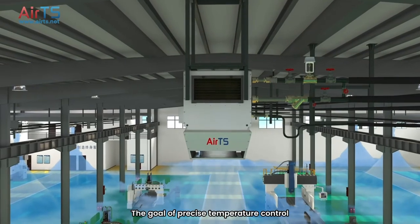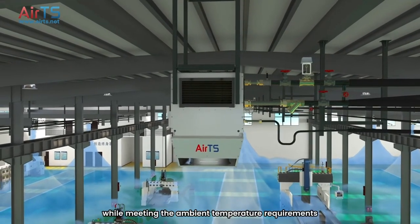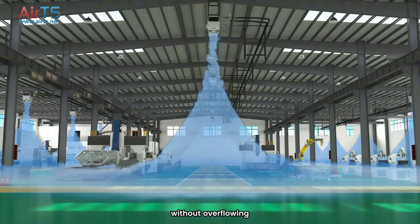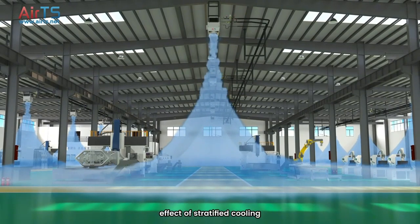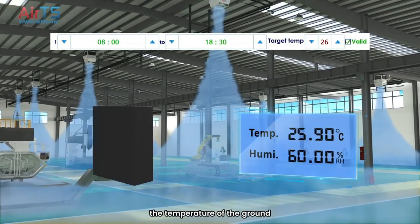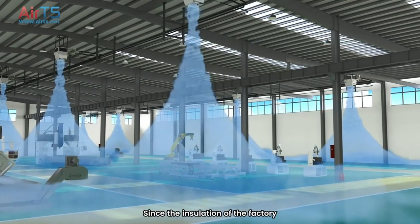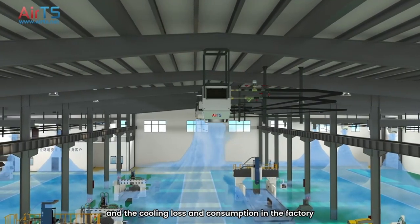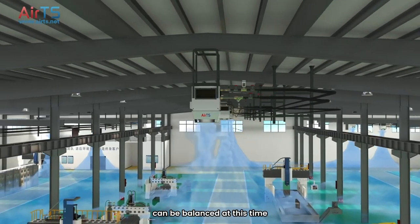The goal of precise temperature control is to not increase the cooling output while meeting the ambient temperature requirements, and try to keep the cooling capacity in the bottom space without overflowing, so as to achieve the most ideal effect of stratified cooling. After the device is running for a period of time, the temperature of the ground working area reaches the target temperature. Since the insulation of the factory with cooling demand is good, the total cooling output of the device and the cooling loss and consumption in the factory can be balanced at this time.